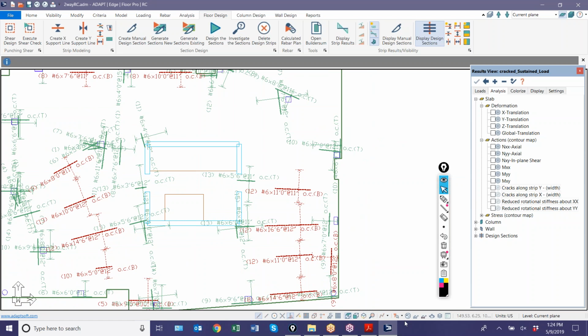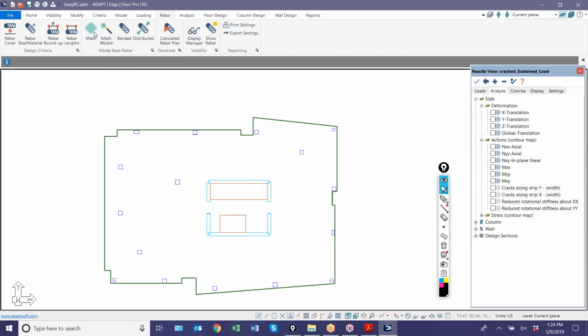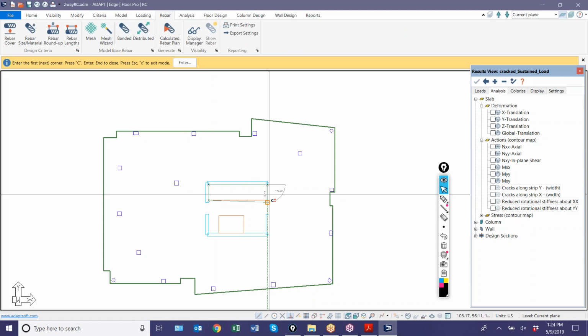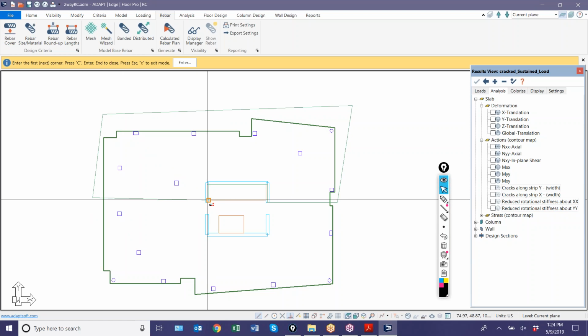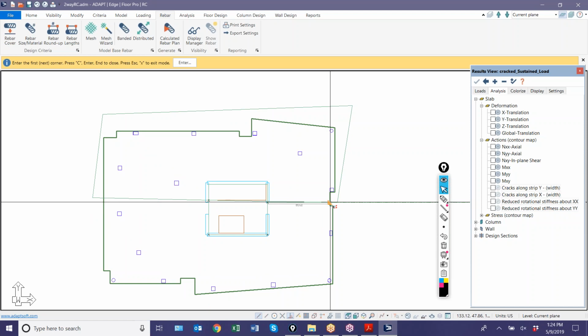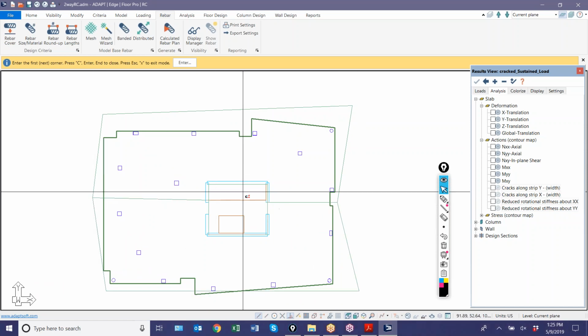But in terms of the mesh reinforcement, instead of using the wizard, I could just create a mesh, and I would literally have to map the rebar. This is just like a polygon input. I would create a mesh maybe over here. I'm not going to place it right on the slab necessarily, and I would create a mesh in this region here. So you might create two mesh regions and nest them around the opening.